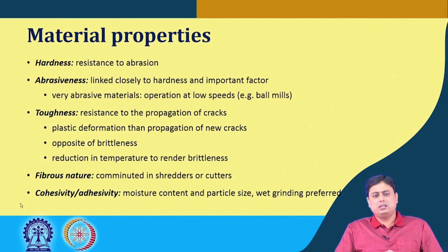So, the discharge or the feed inlet, all these things become a difficult scenario while handling these materials. So, wet grinding in such cases, or handling these cohesive or adhesive materials, becomes immensely helpful for size reduction. That means we have to look into the equipment which can be operated in wet grinding scenarios as well. We have seen the ball mill can handle dry operation as well as wet operation; it can be carried out inside a ball mill.